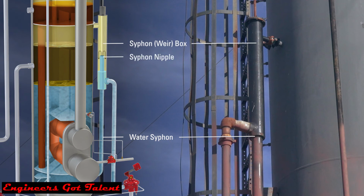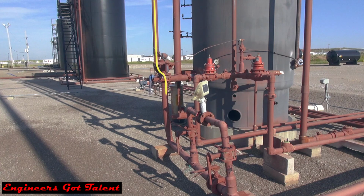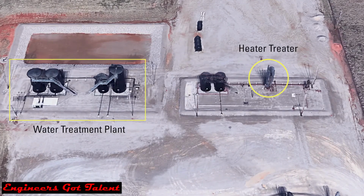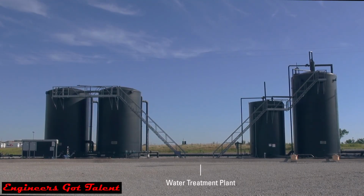As the water reaches that level, the water spills over, goes down this downcomer pipe, and again, the valve controls only the level in the downcomer pipe. As the liquid comes down the pipe, the valve will come open, and the water will exit to either a fiberglass tank for storage, or it will go to the water treatment plant on this location for further processing, and then will be disposed of there.